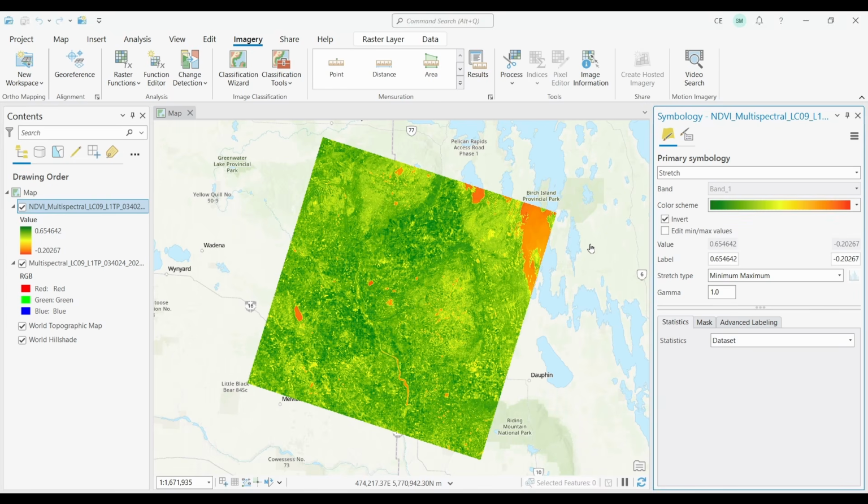The NDVI values range from -1 to +1, with higher values indicating a higher density of healthy green vegetation. Values close to -1 indicate water bodies, such as lakes, oceans, or rivers, where there is little or no vegetation. Values close to 0 represent barren areas, such as rocks, sand, or urban surfaces, with little or no vegetation. Finally, values between 0 and 1 indicate areas with varying degrees of vegetation density, where higher values represent denser and healthier vegetation. You might want to try thresholds like I mentioned to identify areas with specific vegetation densities, water, and